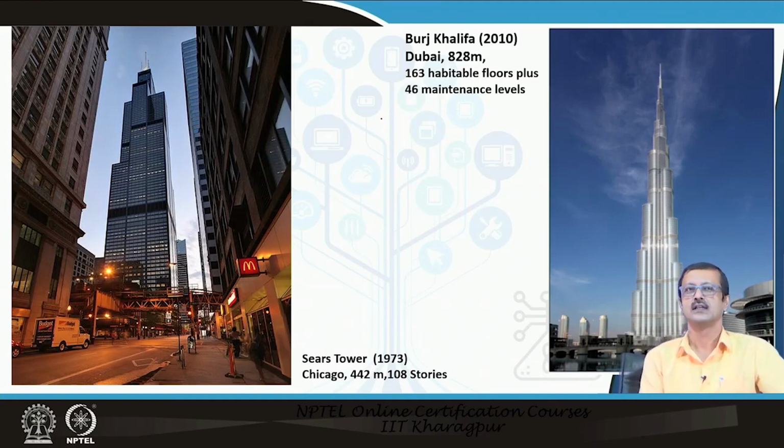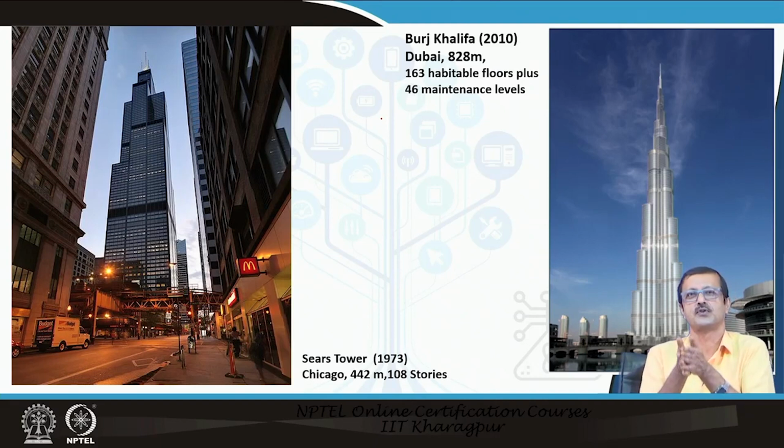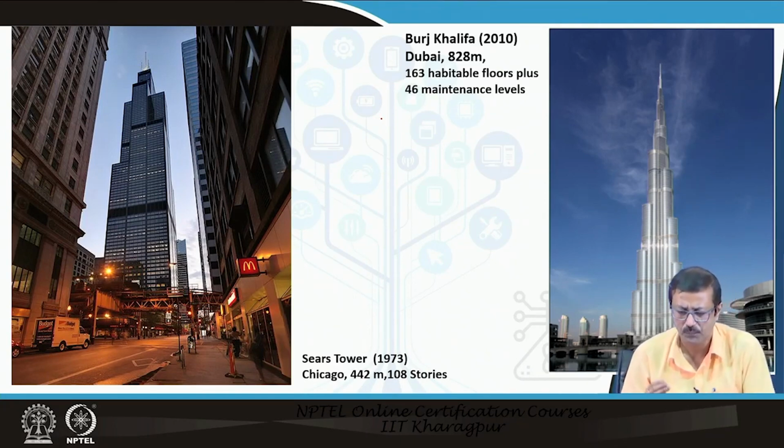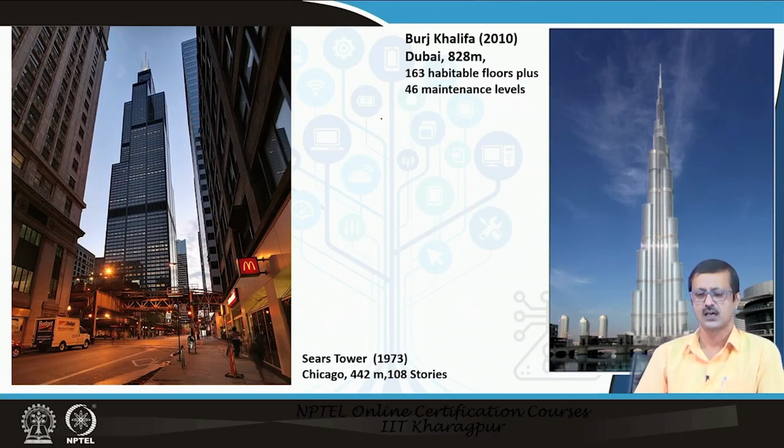We thought in the last lecture of 20 story, 30 story in the shear frame building, the frame shear interaction building may go another maybe 45, 50 floor maximum, but tube systems give you up to 70, 80 something like that. Sears Tower bundle tube is 108 storied. Burj Khalifa may not be perfectly the bundle tube, but there is still some consideration of the bundle tube system, and some other type of structural philosophy has actually been followed.